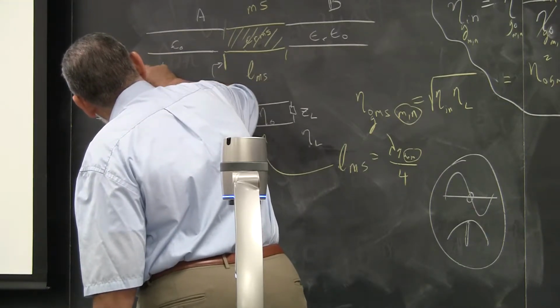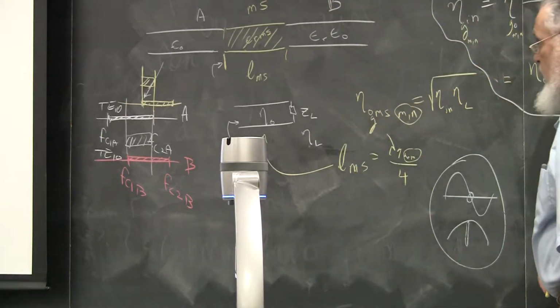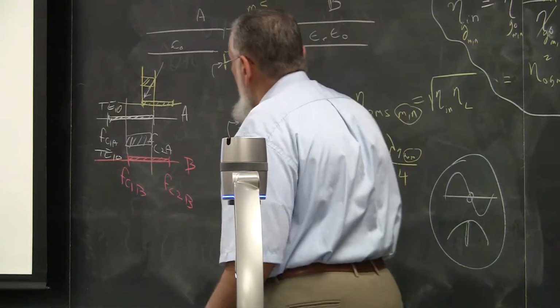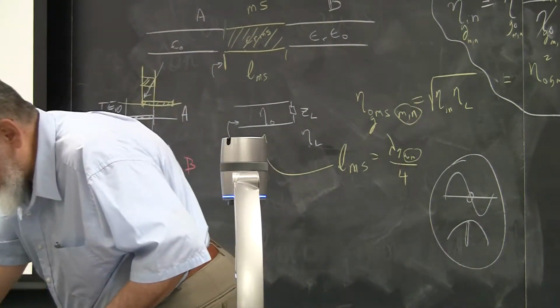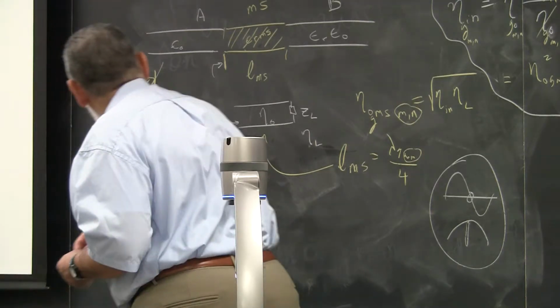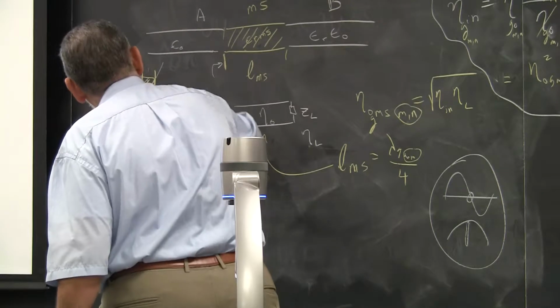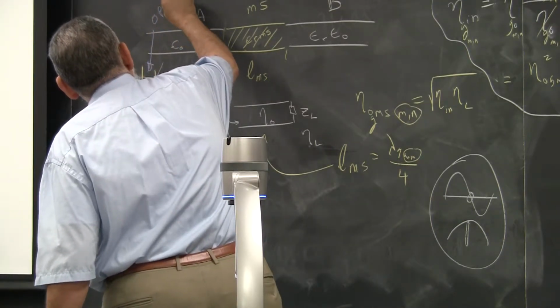So that's now the common region of operating frequency between all three guides. And logically, if you are sending a signal with carriers, your carrier frequency has to be somewhere in the middle of that. So you want to call this here your operating frequency.